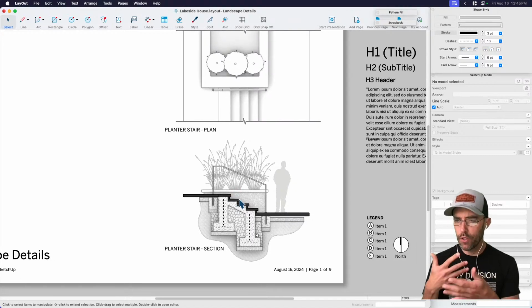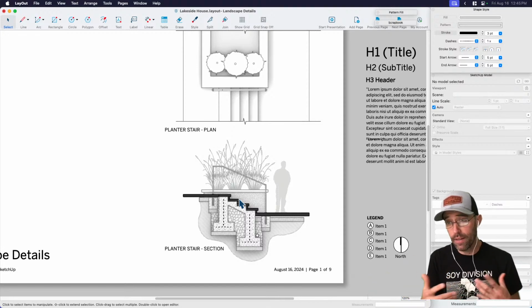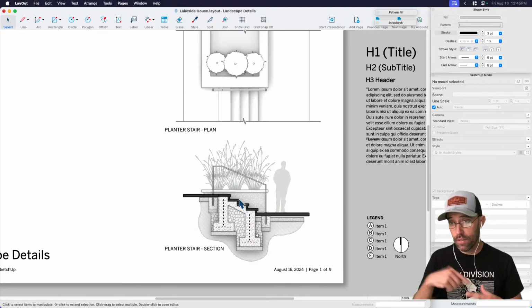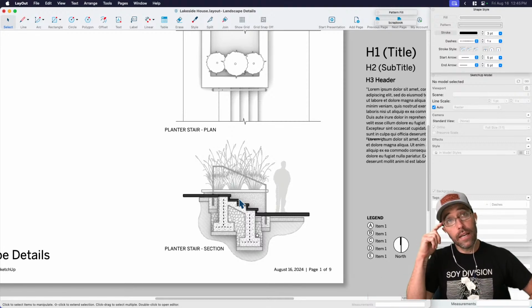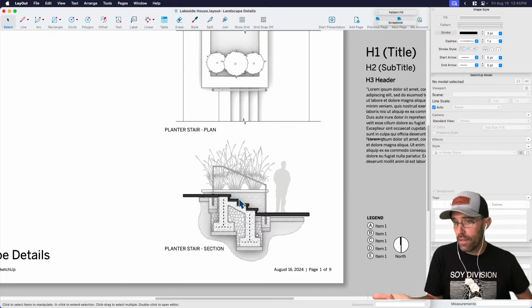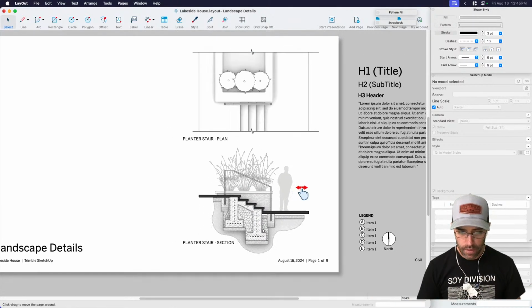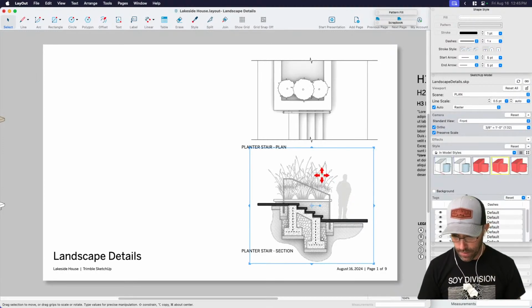Yeah, and then of course it all just depends on how you've organized your model. You could just create a layer, or a tag in SketchUp, called beyond, and then everything you put on that, you just turn everything off except the beyond or the background. You have two viewports, one that's back, one that's front. So it's a little subtle thing, but it can make a big difference.